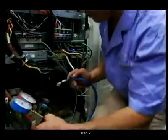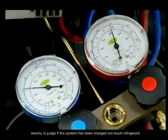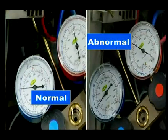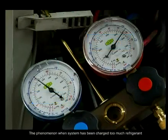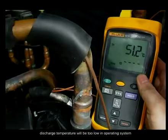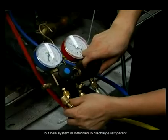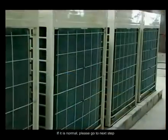Step 2. Measure the system pressure and compare with the normal system nearby to judge if the system has been charged with too much refrigerant. The phenomenon when the system has been charged with too much refrigerant: the high and low pressure will be too high and discharge temperature will be too low in the operating system. If there is such a situation, please discharge some refrigerant, but a new system is forbidden to discharge refrigerant. If it is normal, please go to the next step.